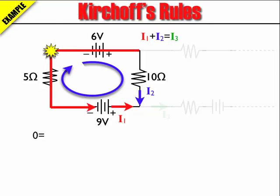For loop rules, remember that everything is equal to 0. So 0 equals all the changes in energy of these four components. As I go from left to right from the star, I go from the star to the negative side of the battery, then to the positive side. The negative side is the lower energy, the positive side is the higher energy. So to go from low to high, I have to add voltage. So for the battery, that's easy. I just add 6 volts. So that's the start of my loop.